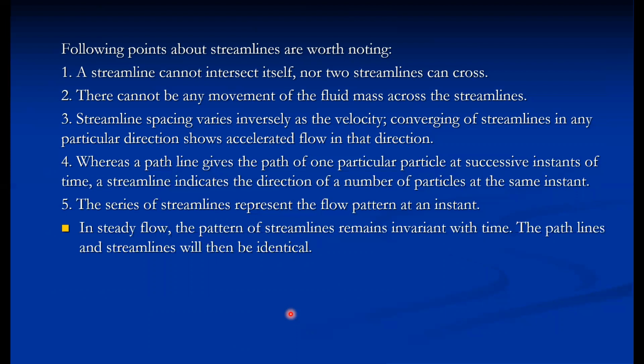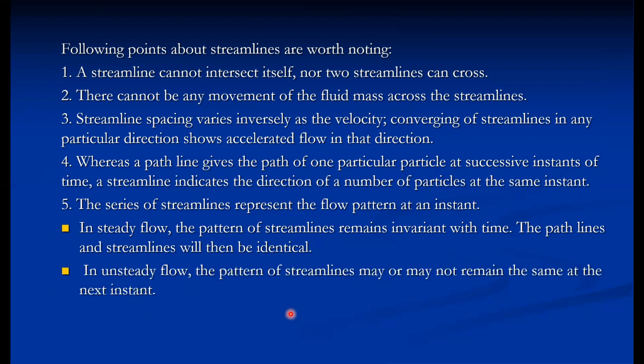So in steady flow, the pattern of streamlines remains invariant with time, and the path lines and streamlines will then be identical. In unsteady flow, rather, the pattern of streamlines may or may not remain the same at the next instant.